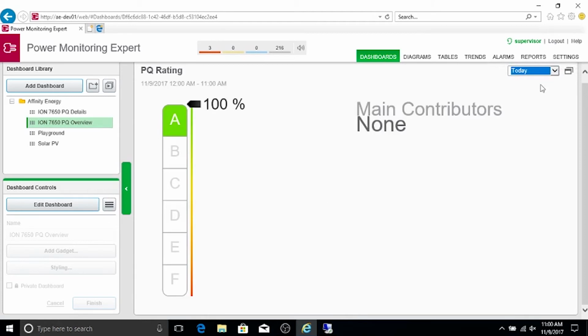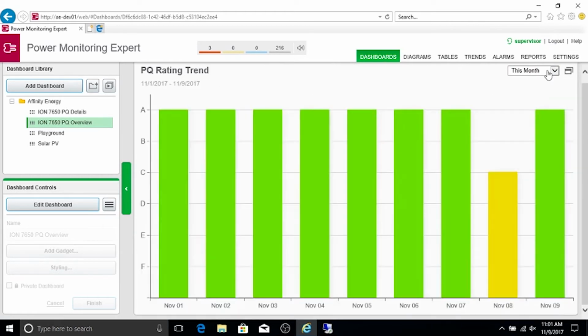So again, depending on when you look at the data, for example, I just picked today. Today we've not had any interruptions, no sags, swells, or disruptions, so you can see that our rating is 100%. We're going to generate a sag swell event in a few minutes, and you'll see how the system detects that, and then you'll be able to see how that rating changes after the experience of a voltage disruption within the facility.